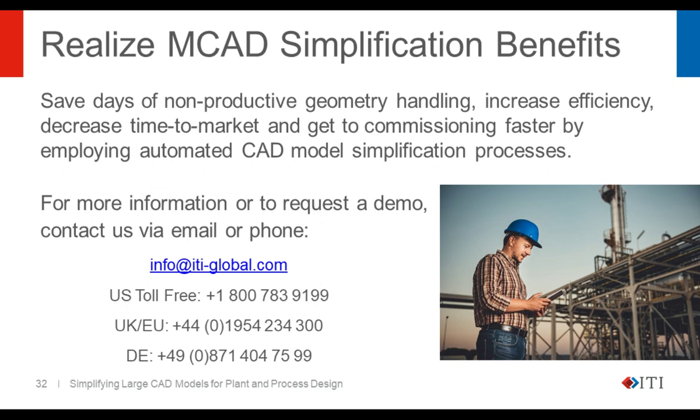And you can also identify parts based on maybe the label or by manual selection to put into a keep list so that then they are not simplified. So there's quite a bit of control. Ultimately, we like to keep the user in control. So they have the options to change the amount of simplification that is performed, and you may decide, based upon particular types of models, to have different configuration files with different options and tolerances to process those models.